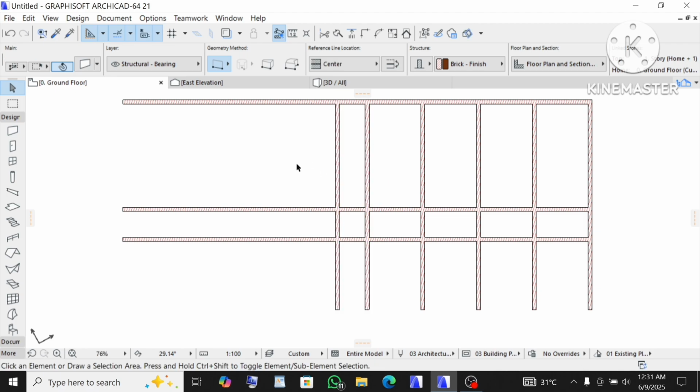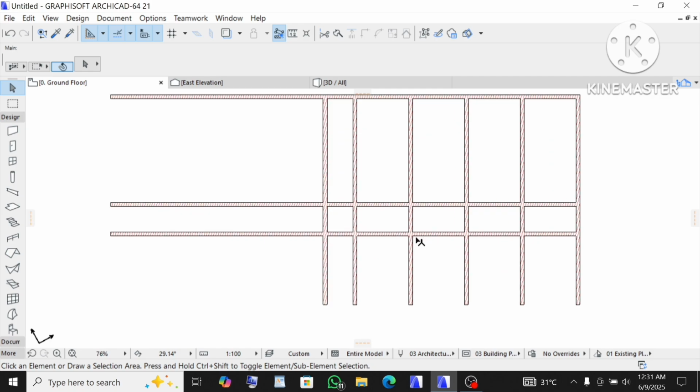You can see that. So now we'll go further by eliminating these stray walls. You can see all these extraneous walls. We're going to eliminate all of them, and to do so, we are going to suspend groups. Make sure you suspend these groups. If this group is already showing blue, then no need, do not suspend. But if it is not showing blue, click on it. You can see I've clicked on it and it's now showing blue. We have suspended the group, and the shortcut for suspending groups is Alt G. Press them on your keyboard simultaneously.